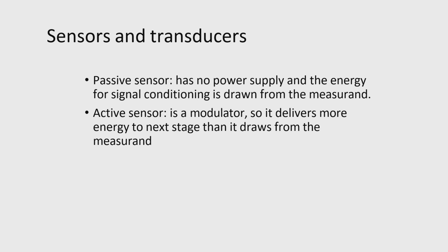If I use a piezoelectric strain gauge and I compress it, then I can get an electrical signal. So, based on that principle I can measure the strain, because it will sense the displacement and convert it to corresponding charge, and finally we have a charge amplifier, etc. Then we can find out what the strain is. Otherwise it can also sense load.